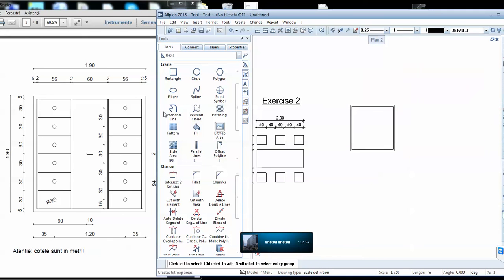And then I want to create this drawing by entering a set of offsetted polylines. With a single move I can create more polylines at different offsets, and I'll do this with the offset polyline function. Number of parallel lines: I say 1, 2, 3, 4 lines should be enough. 4 parallel lines, and now I'm going to mention the distances.